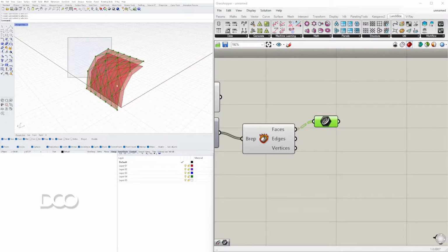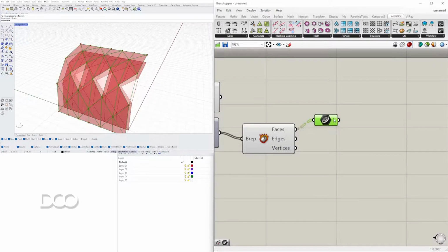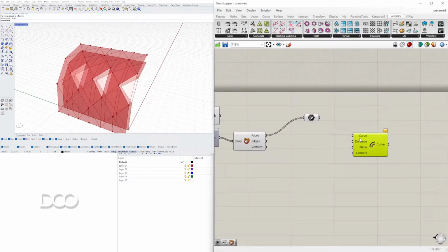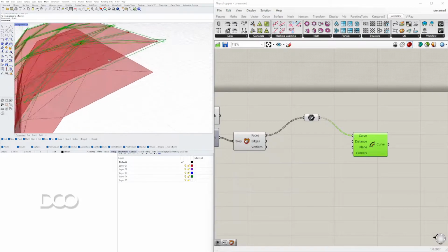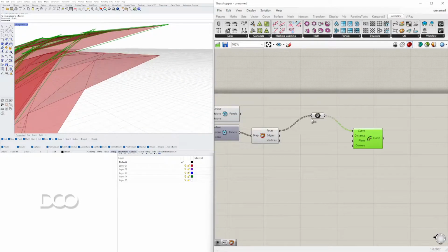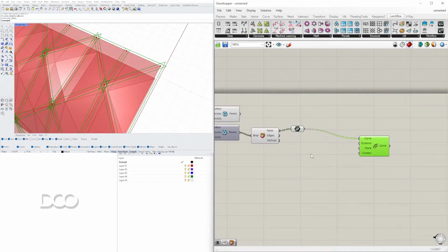So what I'll do is I'll just select all the stuff that I just baked and delete it. Now in here, what we need to do is offset this curve. So I'll go to Offset Curve, and we'll offset this curve relative to the plane that it sits on. So let's go here to distance, because right now it's offsetting to the outside and we actually want it to offset to the inside. So we have to go to a negative component, and the distance will say 1.5.